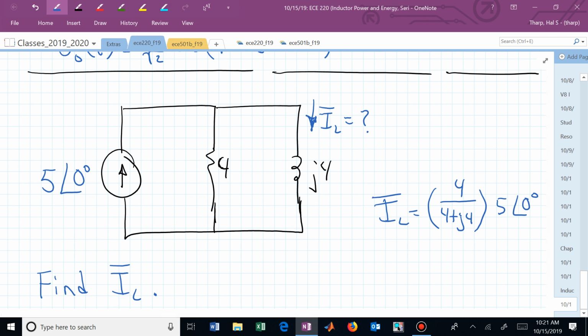By what? Multiplying and dividing the magnitudes and adding and subtracting algebraically, appropriately, the angles. And then you have a complex number. That's all there is to it. Don't get too excited when you go into the phasor, the frequency domain. You know how to do it. It's just now you have to get a little more comfortable playing with more than just real numbers. Now you're playing on a plane. Now you're playing with complex numbers. Real part and imaginary part. So we'll pick up with capacitors tomorrow.